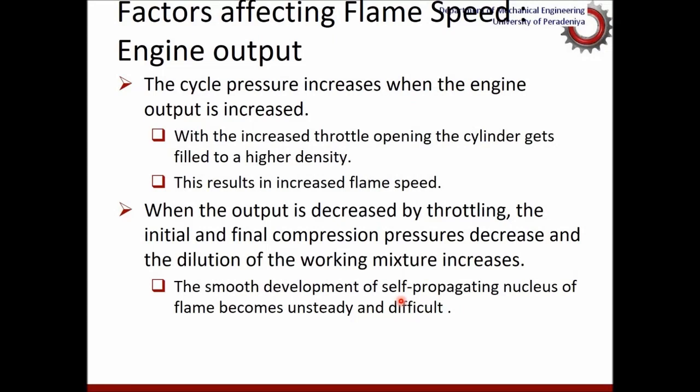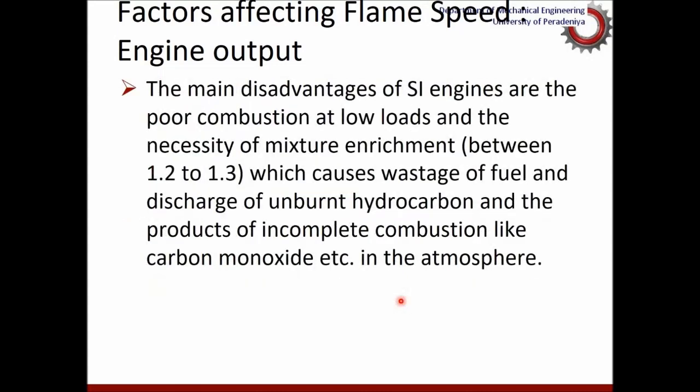So that means the combustion under low pressure conditions is not very steady, therefore there can be some abrupt changes in the engine process or the pressure and temperature development within the engine. Accordingly, there can be some instability within the system. So that is one of the problems with internal combustion engines running under low load conditions.